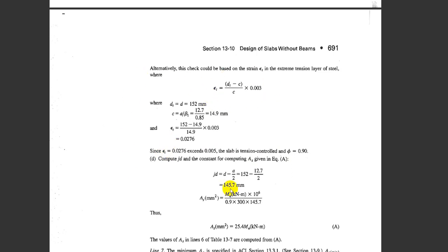These are all things that we learned in RC1, and I repeated in the column section. So you can go back to the column section to see how to calculate the rebar strain based on strain compatibility. I also gave you a lecture on how to calculate the phi factor based on the ductility, which is a function of the strains of rebars.